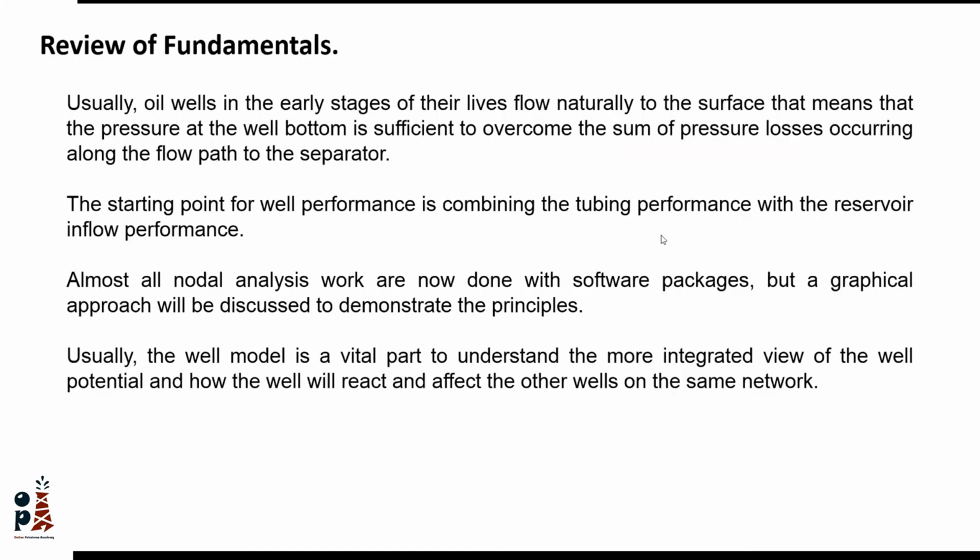If we review our fundamentals, a new well which is drilled normally has the capability to flow naturally. That means that this well will have the capability to overcome the gravity of the well fluids inside the well and deliver the well fluids to the surface with a certain pressure that will be capable to push these fluids to our facility, which we call the wellhead flowing pressure or the wellhead back pressure.